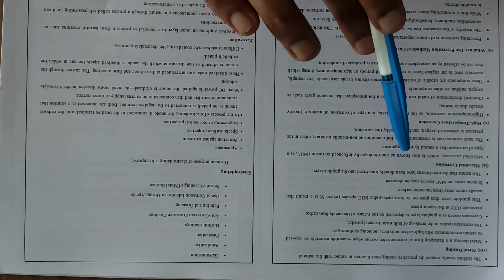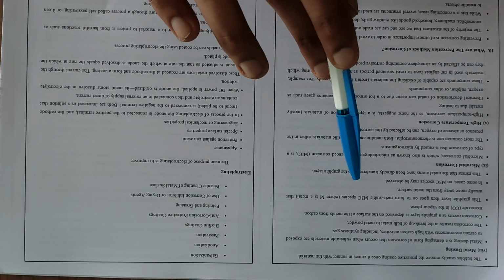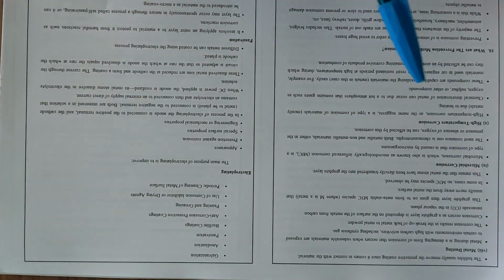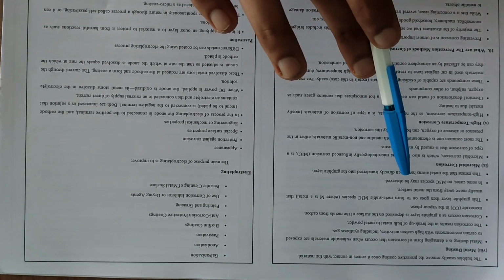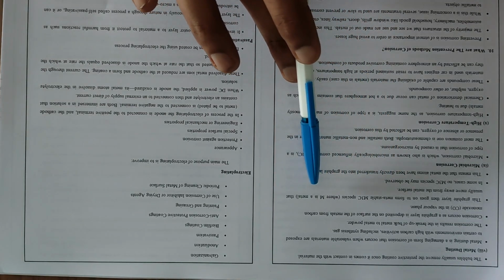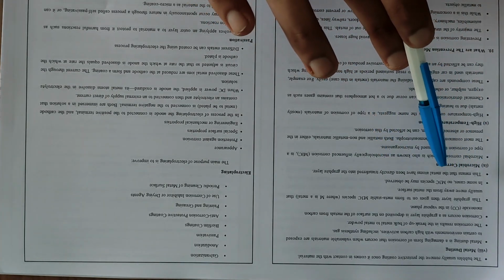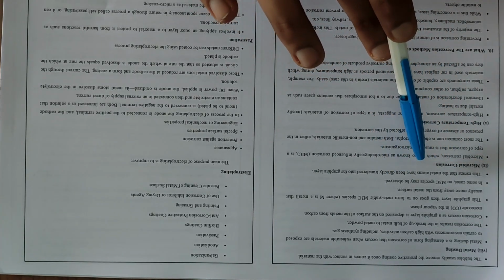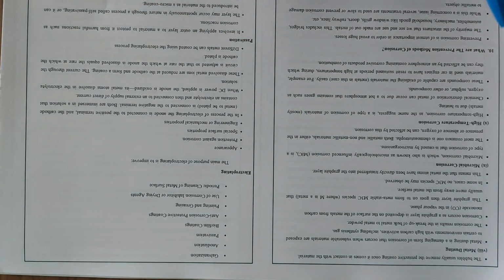Corrosion occurs as a graphite layer is deposited on the surface of the metal from carbon monoxide (CO) in the vapor phase. This graphite layer then goes on to form metastable M3C species, where M is a metal, that usually move away from the metal surface. In some cases, no M3C species may be observed. This means that the metal atoms have been directly transformed into the graphite layer.